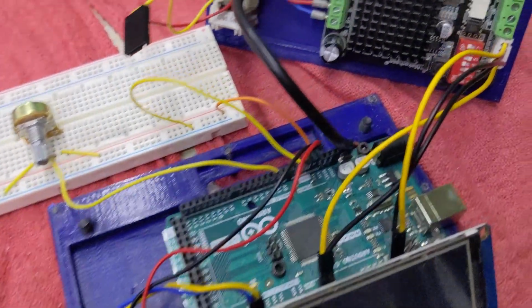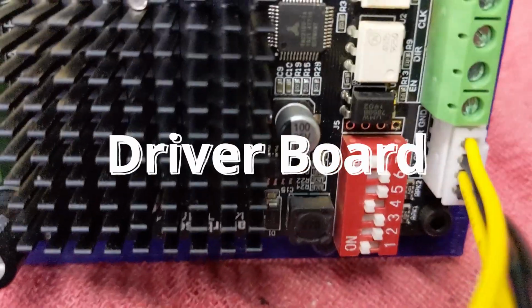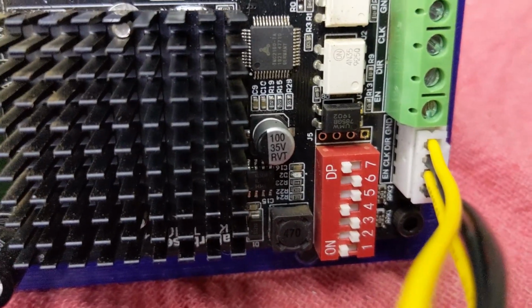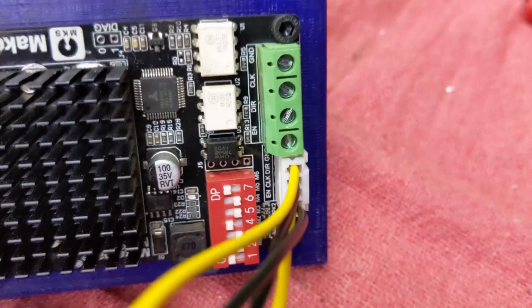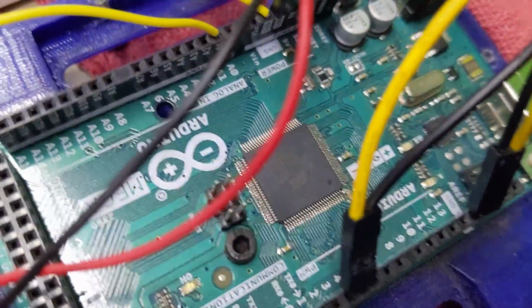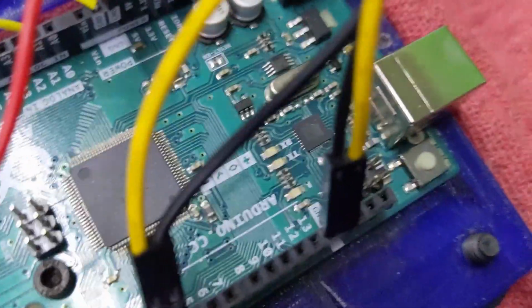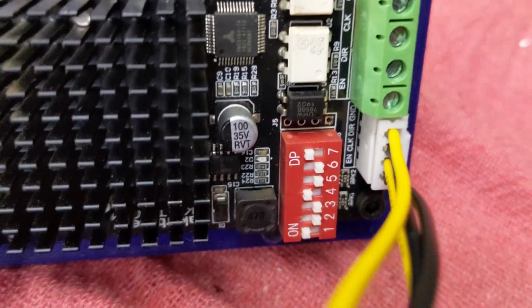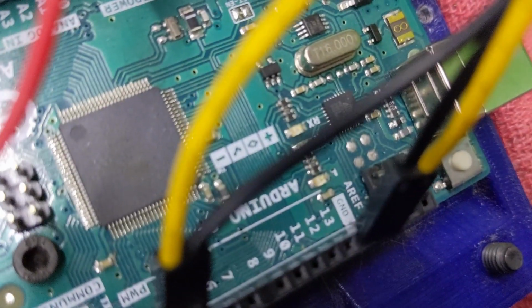Okay, I got everything set up again. And I've got clock, enable, clock, direction, and ground. And clock is step in the Arduino sketch. So those need to be wired into the correct ports here. Step is 3, which goes to clock. Direction is 4, and that needs to go to direction. And then enable and ground. Enable needs to go into 13, and ground needs to go into ground right next to it.